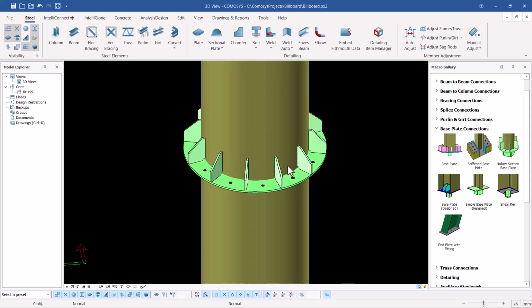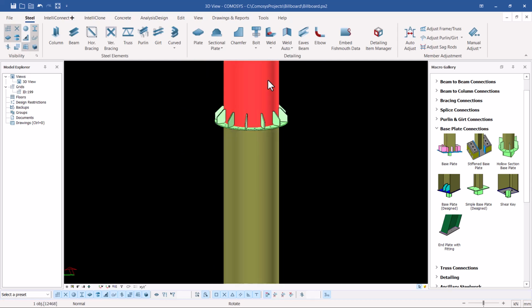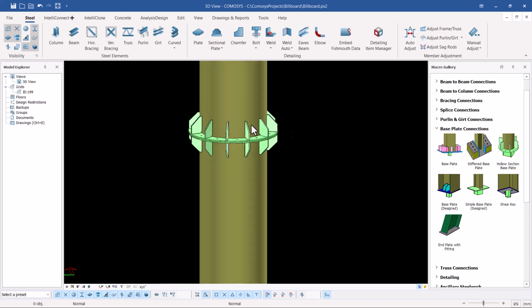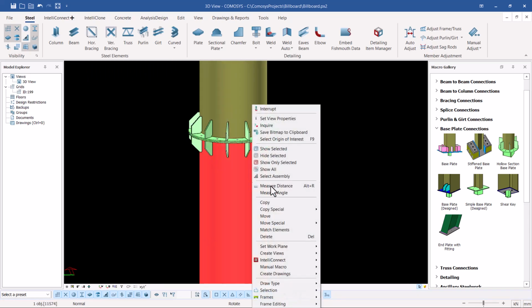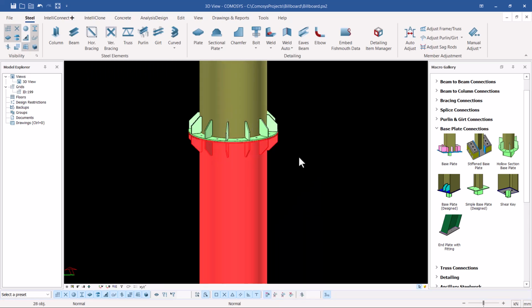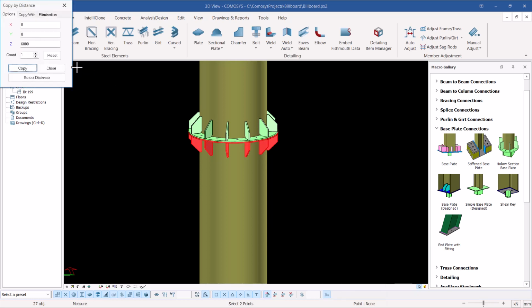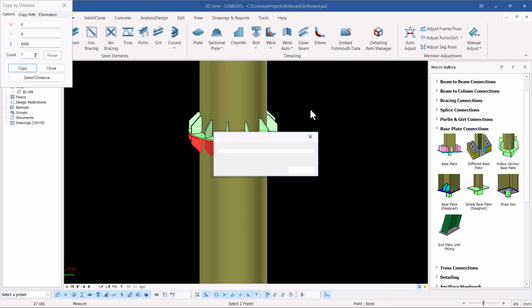So if I click on that spot and try select this and check whether it is an assembly, we'll be able to see it is an assembly. So that's how simple it is. So if I select this once again, right click and come to special copy and select an assembly, I can remove that from the selection, then just right click here and copy it upward at a distance of 6 meters and click right there. So let's see what happens right there.